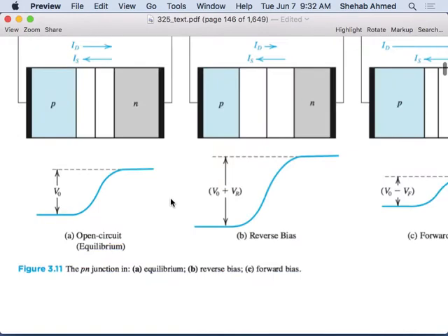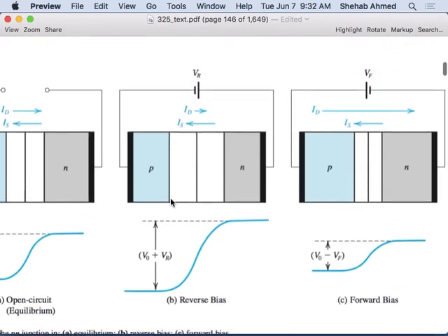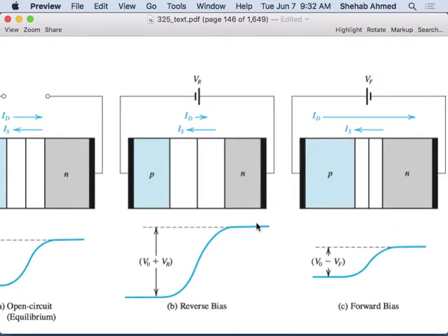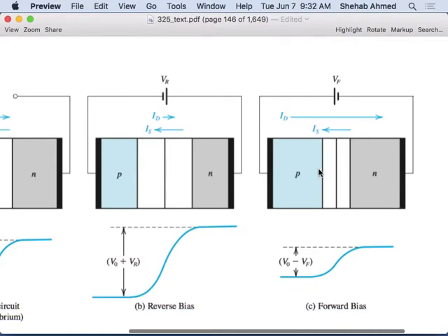So when it's forward bias, it basically decreases that depletion zone, so it makes it easier for diffusion to happen, because you have less electric field. You've opposed the electric field generated by the barrier, by the junction, so by the barrier voltage, basically. And what is reverse bias?